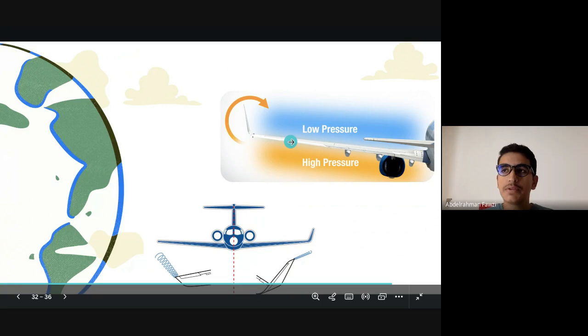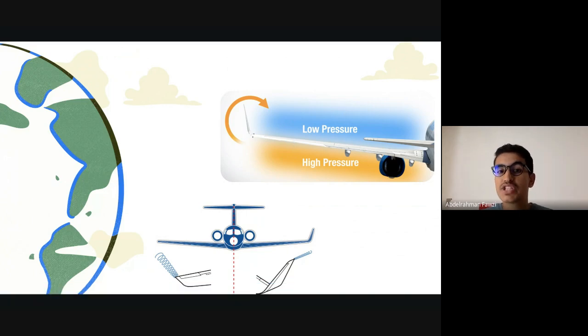And then we implement something called winglets, especially when your wing is actually short. This is for the narrow body airplanes, which usually have this winglet. It increases the range, it lowers the friction, lowers the cost, less fuel consumption, and so on. How it works: it creates a longer surface for this high pressure to move. And also somehow it creates a wider wingspan. But this is not the main purpose of implementing them.